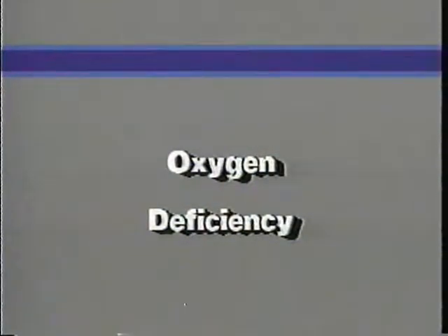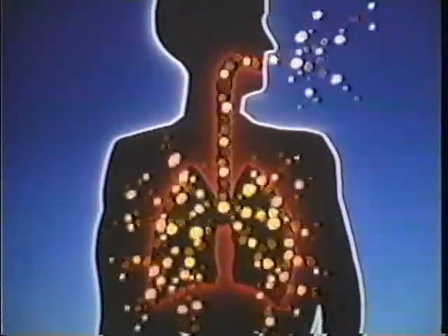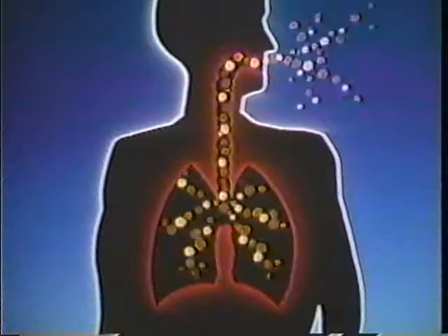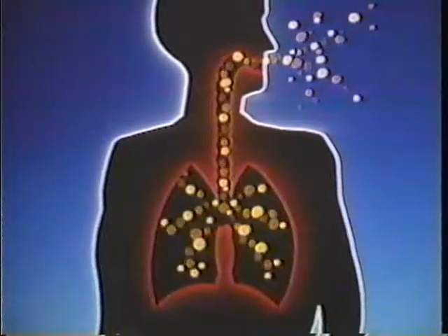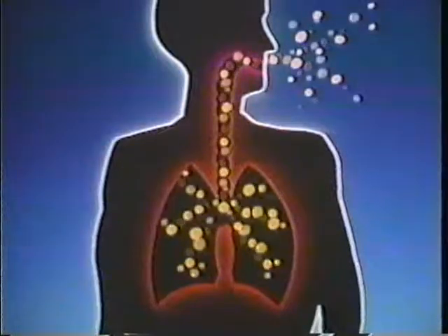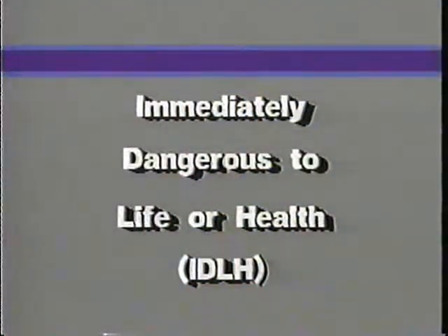And remember, in many instances, the contaminants which can cause damage to our bodies are so small we can't see them. And there are 2 other hazardous conditions you must be aware of. One is the lack of oxygen in the air. If the oxygen concentration falls below 19.5% oxygen by volume, people become dizzy, experience ringing in the ears, and can eventually die. A second hazardous condition exists when concentrations of contaminants are immediately dangerous to life or health, known as IDLH. If either of these 2 conditions exist in your workplace, a safety professional must be consulted.